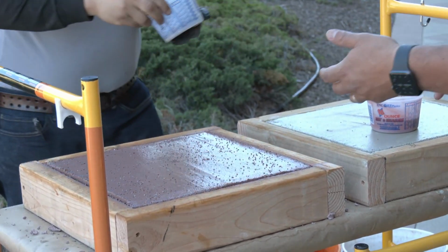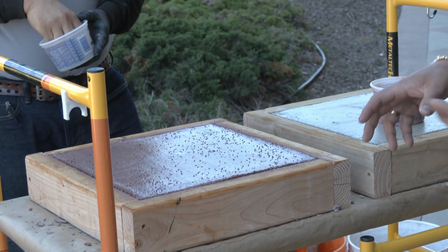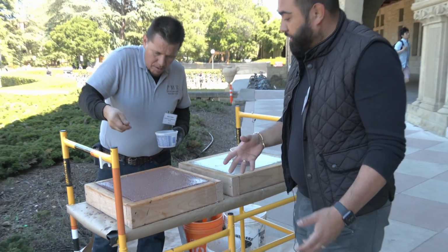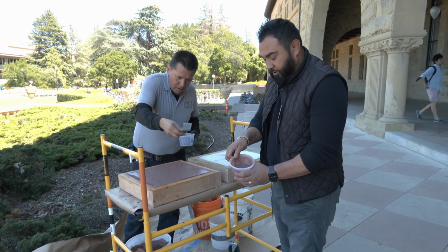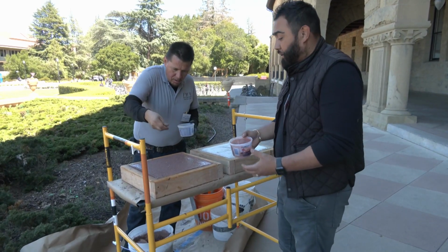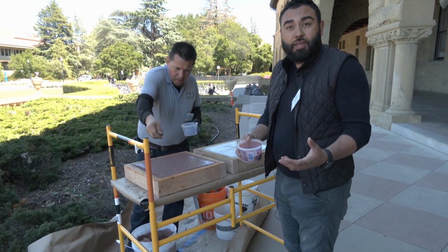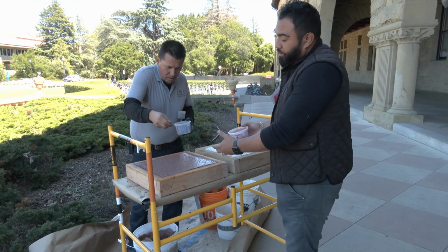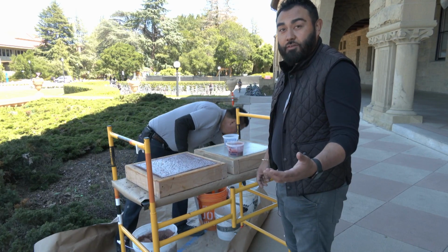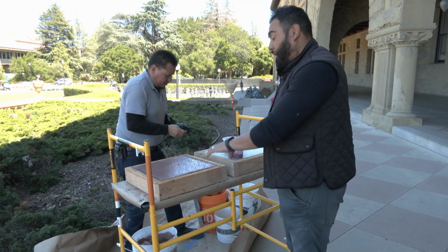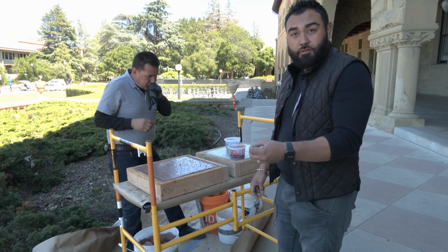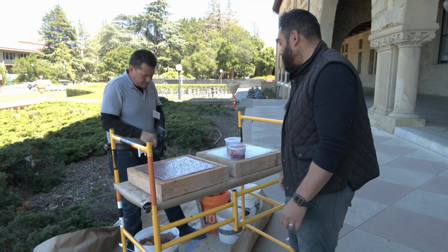He's broadcasting at this moment what we like to call salt and pepper. Originally, the red aggregate was integrated with the sand. Obviously, we can't get our hands on that sand anymore. So to match the existing color and aesthetics of the paver as close as possible, we have to broadcast each paver with the red aggregate.